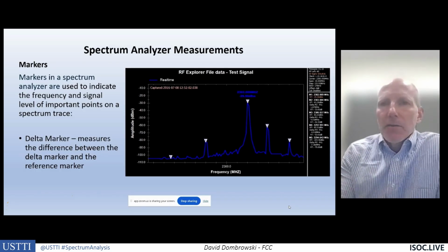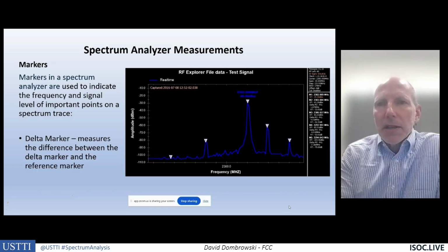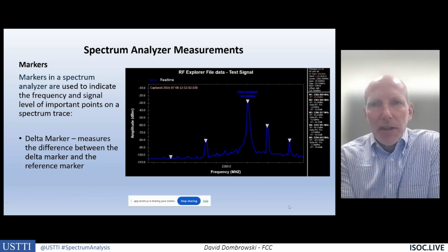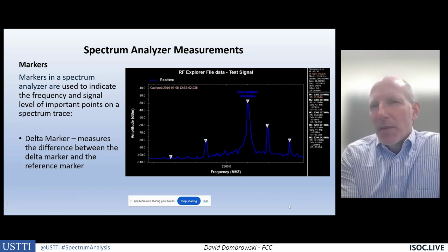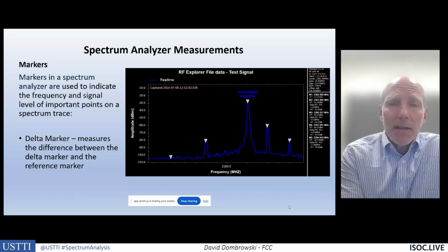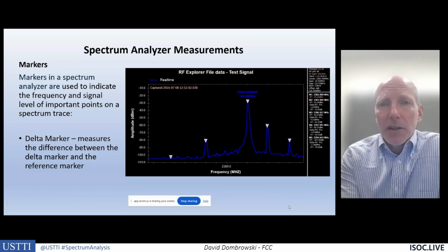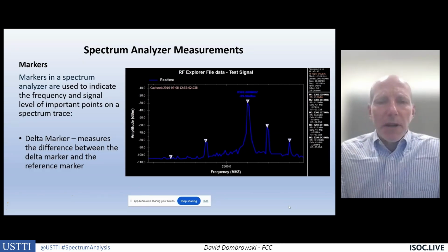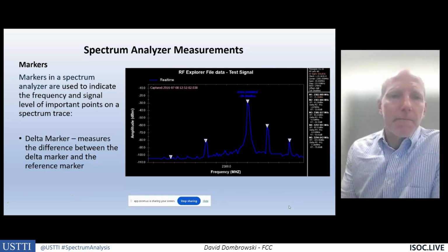Maybe something inside the room or the building is causing interference. Maybe a computer can put out emissions when it's very close to the antenna. So you should sweep the building first and then tap into the antenna to look for the interference source. And if you tap into the antenna and you're not seeing anything, then maybe it is internally generated intermodulation. Hopefully that answers the question. I won't go too deep into that because it is another presentation.